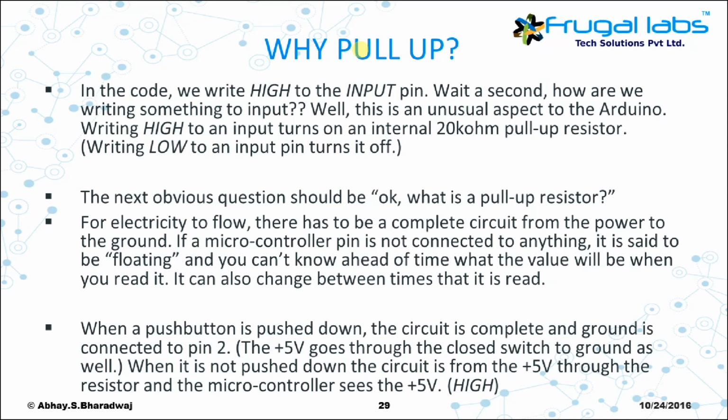When the push button is just connected to the Arduino D5 pin without anything, when you push it, you don't know whether it was on or off previously, right? Now when we introduce the pull up resistor, by default you'll be getting 5 volts on pin D5. So D5 will always be getting 5 volts. Whenever you read D5, 5 volts will be there.